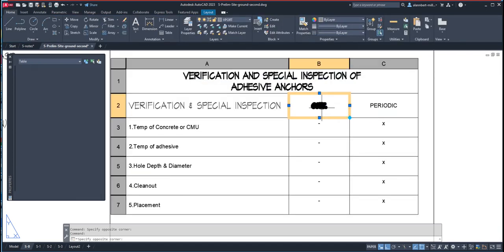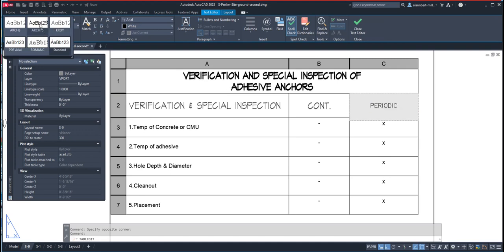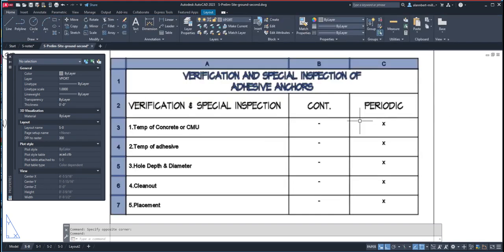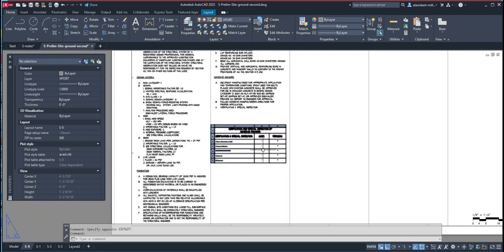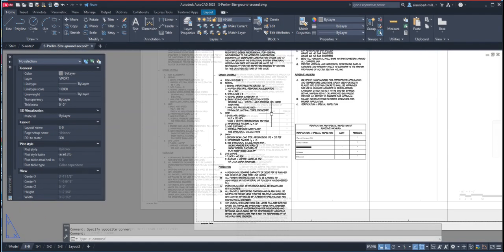Oh, we didn't double click. Click that, and then it didn't highlight. And then we just change it to by layer. Change it to 1/8. Okay, same thing here. Sometimes when you highlight it and change something, it loses its selection. So now see that it lost my selection. So make sure that you highlight it again before you change a property. Okay. And then you want this to say by layer. So when you put it to notes, then it's just fine. Okay. So make sure that you change this also, and then you locate it where you need it, and then finish the rest.